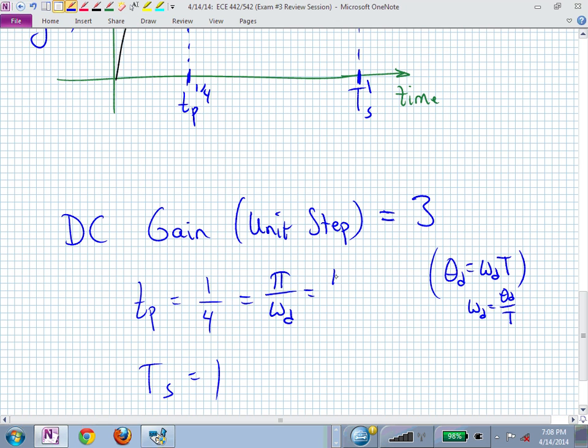And if we plugged in that, now we know maybe how many, if somebody gives you the sample period, I could either give you that time axis in sample periods or in absolute time. If I've given it to you in absolute time, I might need to give you the sample period, and then you can figure out what is time to peak over t, or you know what t is, and now you can solve for theta sub d.